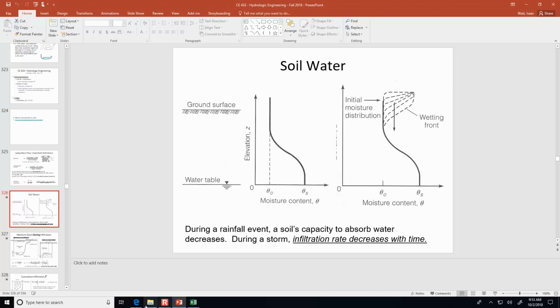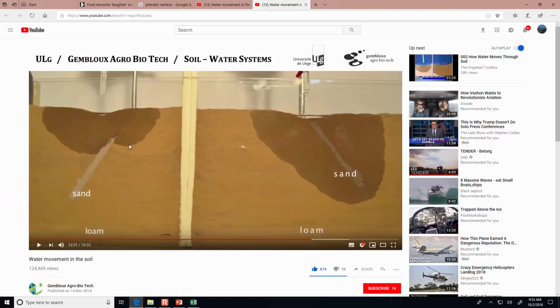And that's what we're seeing in this video: it may be saturated at this point, but this isn't fully saturated. If it was, it would be penetrating through the sand, because we see what happens when the voids are fully saturated. The sand immediately becomes like a highway for that water to pass through because it has such a high hydraulic conductivity. That hydraulic conductivity effect doesn't kick in until saturated conditions. So I just wanted to pause. We'll continue finishing the video there.